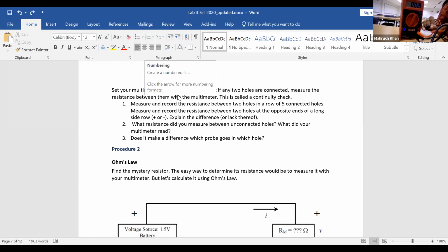Because the power rails are connected to each other. And if you connect it to the other negative part, which are not connected to each other right now, like this, then you will not see any change. So this is a continuity check we will be doing, and if I connect both, you can see the change too, because they are connected to each other. So that's how you can see your continuity check, okay?